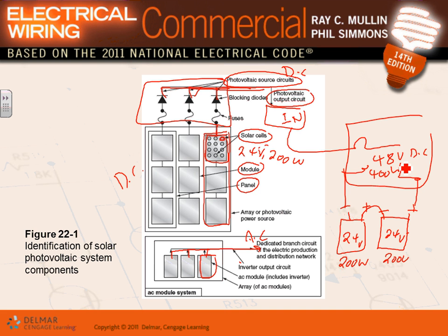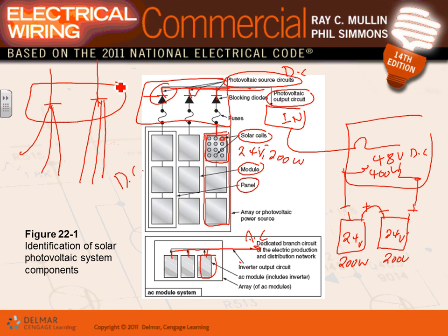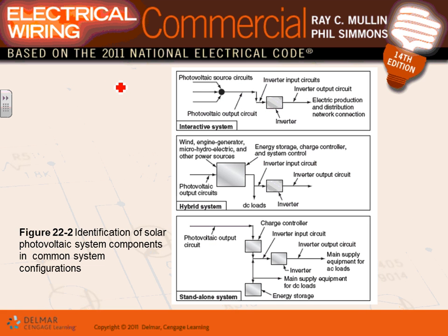So, Derek, they get the voltage by seriesing these panels, and they get more current by paralleling them. Here's string number 1 has, say, 200 volts. String number 2 has 200 volt. You tie positive to positive, negative to negative, you got yourself 2 strings. And they tie these strings right here. So when you see that point here, this is positive, this is negative, and they connect all the negative together, and they connect all the positive together here, and then they take it. That's your so-called combiner. They combine it. Okay, so that's my solar photovoltaic system.